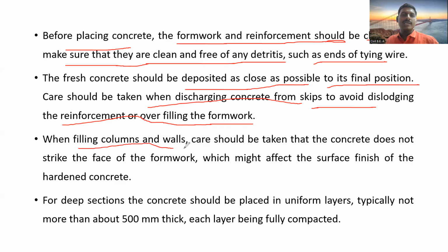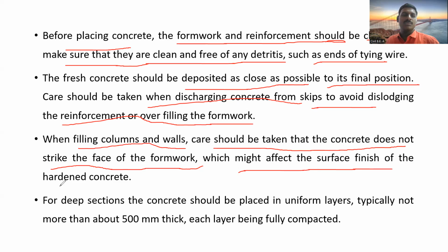When filling columns and walls, care should be taken that the concrete does not strike the face of the formwork, which might affect the surface finish of the hardened concrete. So the concrete should not strike the face of the formwork while being placed. Do we take that much care? We don't.